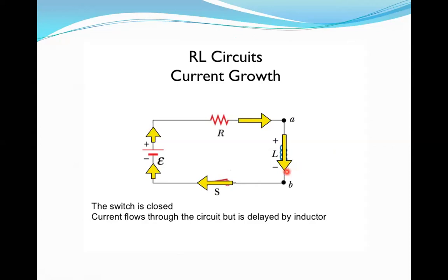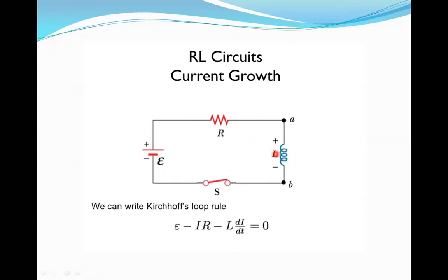According to Ohm's law, V is equal to IR, and so the equation will be E minus I into R minus L di by dt equal to 0. Earlier we have seen the potential difference across R and also the voltage difference across L. So E minus IR minus L di by dt is equal to 0, which is what we get when we apply Kirchhoff's voltage law.